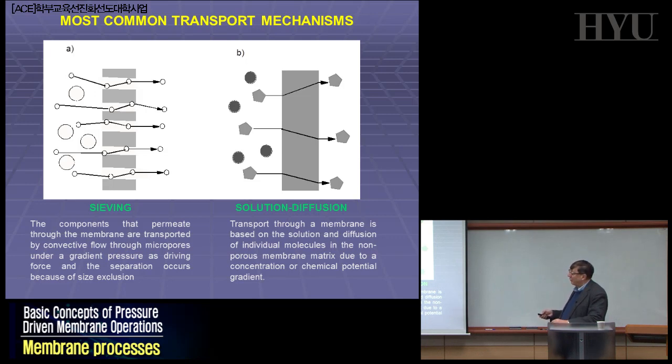And when they are dissolved, you are increasing the concentration of these species on the membrane surface, which is much lower on the other side. So you are creating a different concentration of these species between this side of your polymeric phase and the other side. So you have a concentration gradient, and so these species will diffuse across following Fick's law. So you have one thermodynamic phenomenon, solubilization.